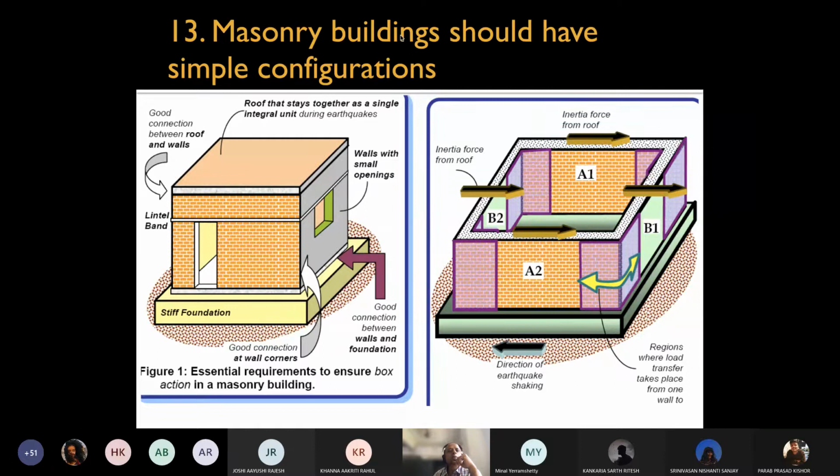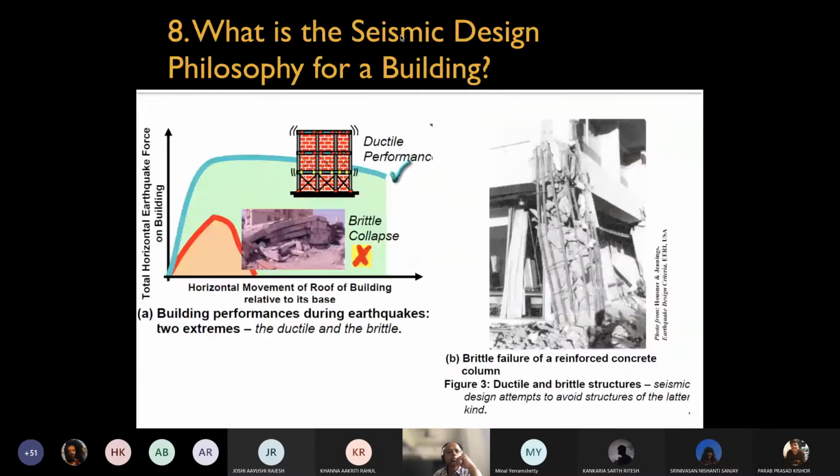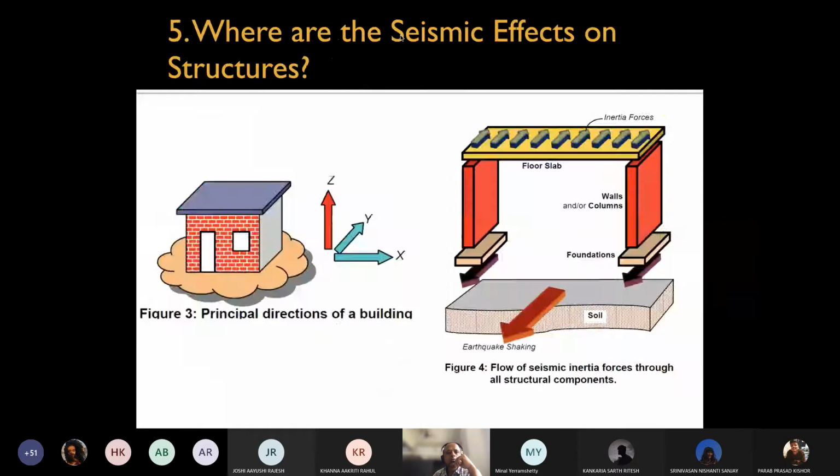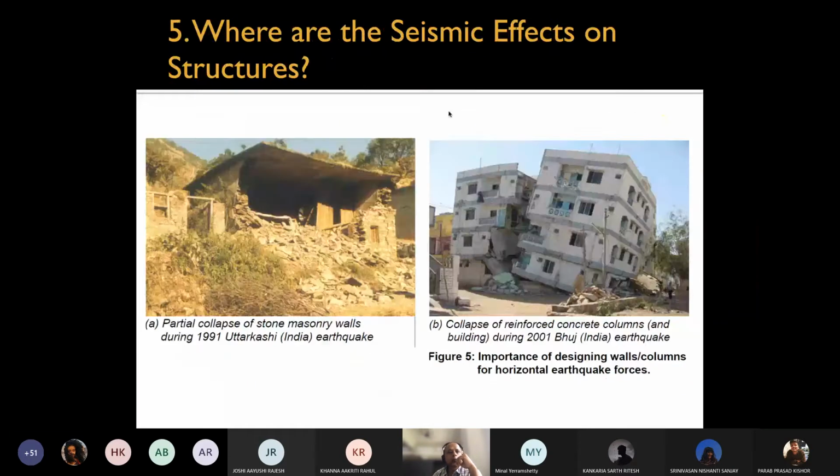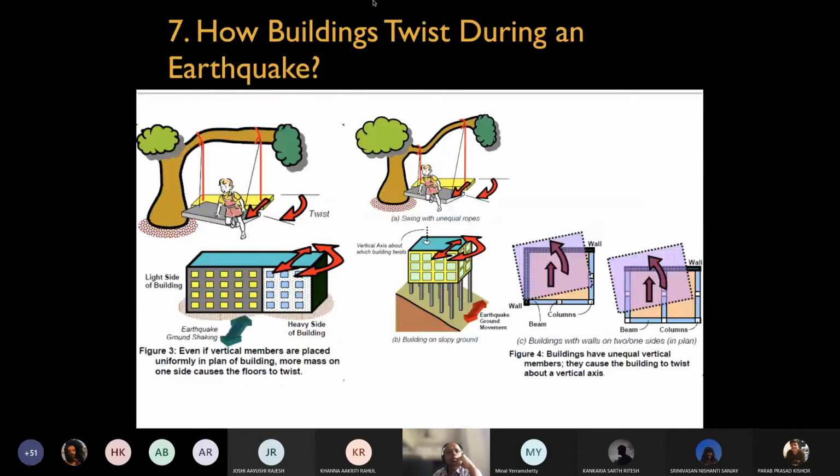Okay. If they are left alone, then you see the result which we had seen in a slide much earlier, which I had shown you. This one, right? So over here, the wall and the roof was not connected properly. The corners were not tied properly. There is no lintel band which is seen. So nothing which you are now seeing is evidence over here, and that is primarily the reason why this kind of buildings, this kind of masonry structures have failed, right?